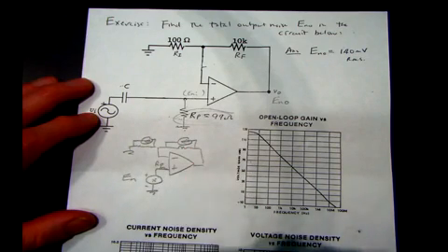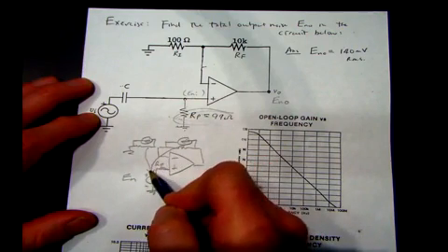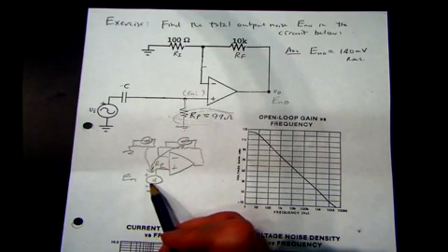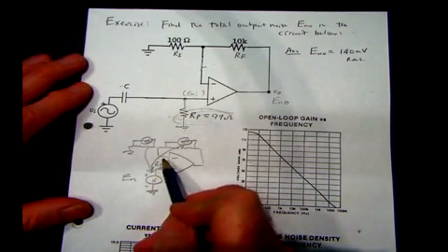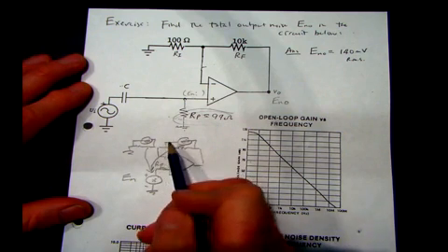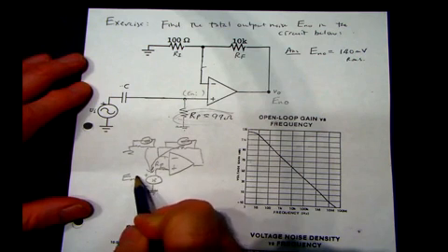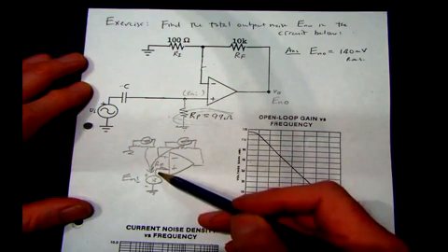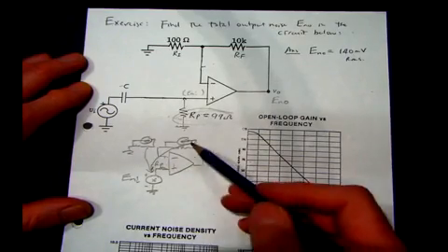Well, it turns out that all of those get lumped in with the voltage noise at the op-amp input, plus the effects of the noise current at both inputs flowing through those resistors, and we get an overall thing that we call E sub Ni, which is input noise, and that will effectively be amplified by the gain of the op-amp.